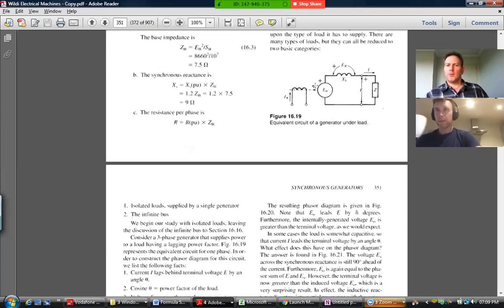And the beauty is that we can control this E0 simply by adjusting the exciting current, and we can see the effect of that on the no load saturation curve, which I won't jump to now. But there was a graph showing exciting current versus induced voltage E0 for a particular generator.